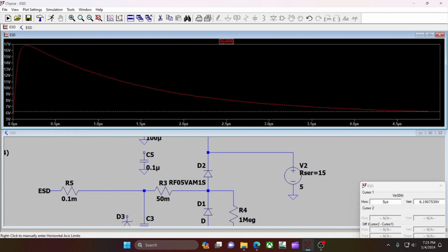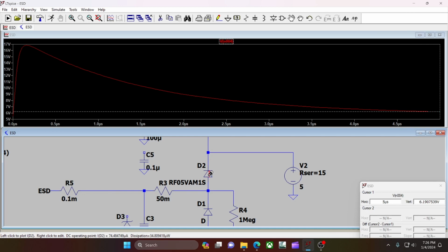I don't know. But point being, we got that 400 volts down to something manageable. You can't have more than the absolute maximum for this very short duration. It won't hurt it. Just remember, we're trying to divert as much of that energy as possible. So if this has to take on a little bit, yeah, that's what it's there for. It's what it's designed for.